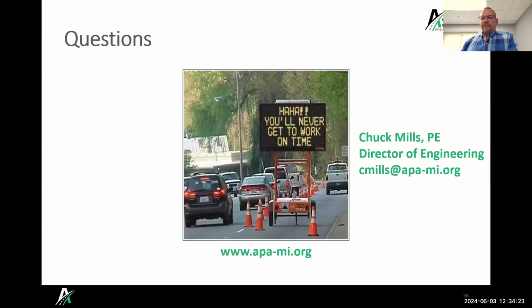That's why it's important as you're processing the RAP. Usually how we get a RAP pile is we mill up an existing road, bring it back to the plant, throw it in a pile, and then we process that RAP. We're crushing it down to different sizes so that we can better incorporate it into the new mix designs.